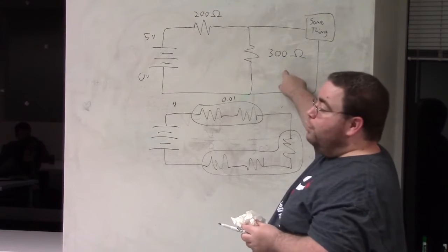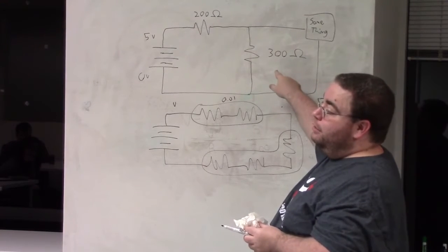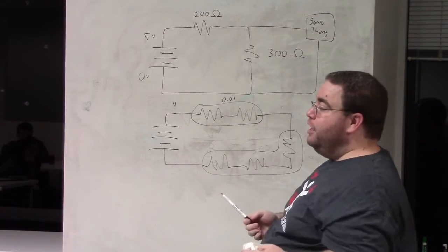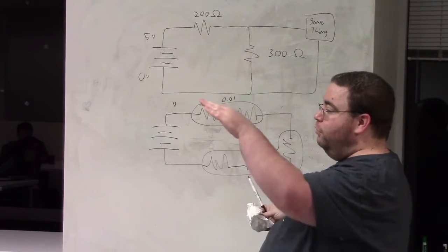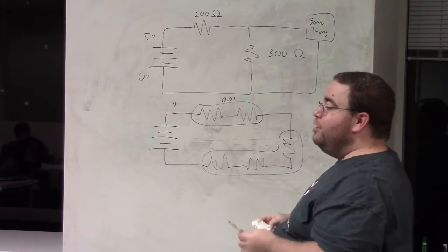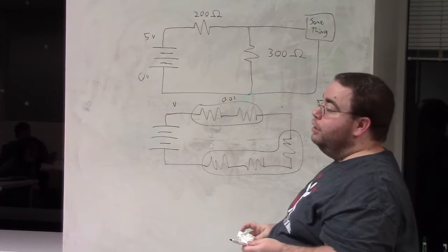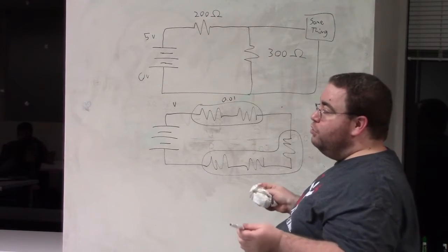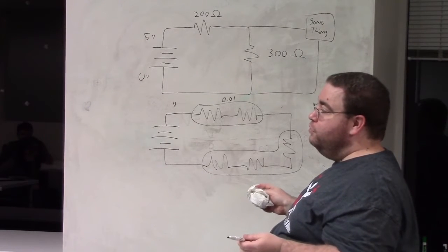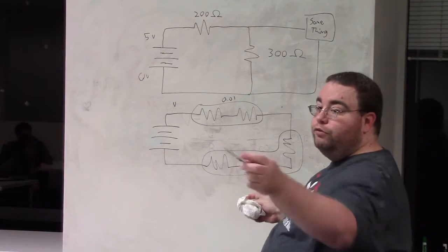This, though, would work perfectly for a signal line, where you're not going to be sending a lot of current down it. You're just going to be either bringing it to 3 volts or to 0 volts. For powering, you probably want to use a linear regulator, though. And again, that's what I've been told from doing this for a few years. That guy probably knows it for real.